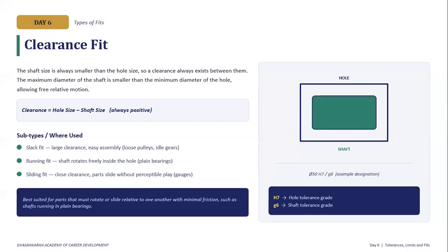In a clearance fit, the shaft is always smaller than the hole. Therefore, positive clearance always exists, allowing relative movement between the components. Typical applications include sliding components and plain bearings.